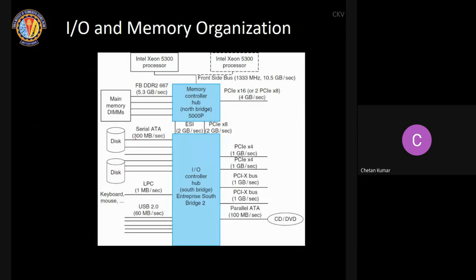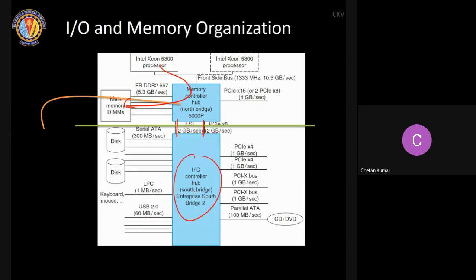So this is just giving an idea about the entire thing that I talked about. Typically, you have one of the buses which will interact with the processor and the main memory. This is typically synchronous in nature, and this is proprietary. Then you have another bus which is interacting with IO devices, and this is basically your backplane bus that I talked about. Here they use general protocols like PCI, SATA, USB, UART. All of those bus protocols will be used for communication here.